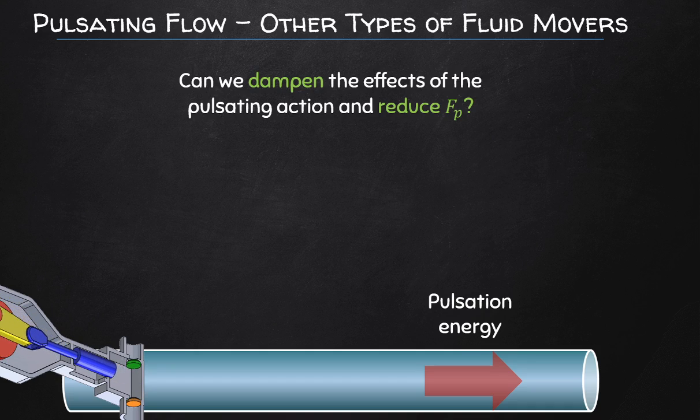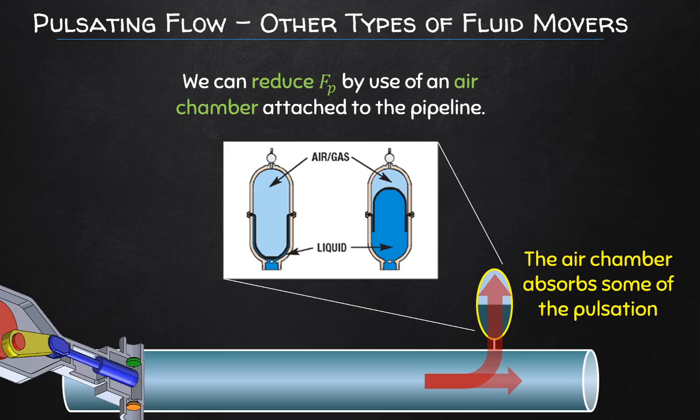So, for example, you can include a gas chamber that contains a compressible fluid, such as air. If this is methane, then air is not a good idea. Air plus methane plus compression means big bang. So you would probably use CO2 instead, if this was liquid methane. But I think if it was liquid methane, you'd probably also liquefy CO2, so you'd have to think of another thing that you could do.